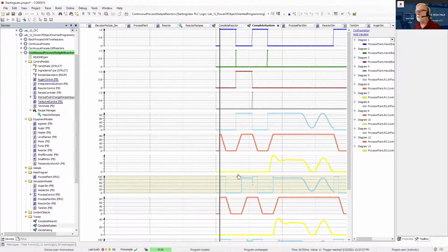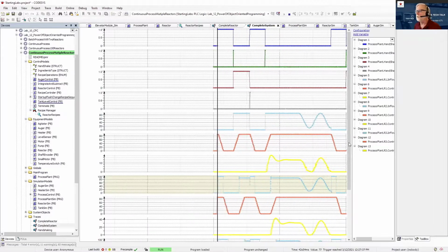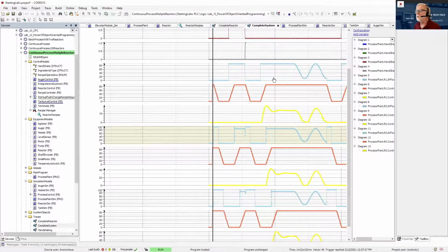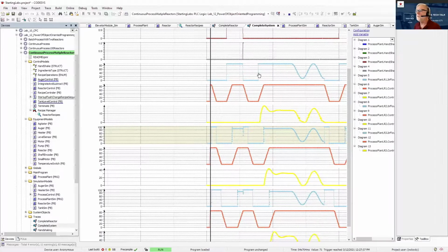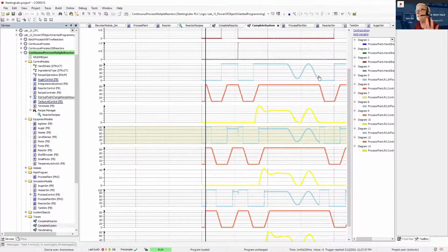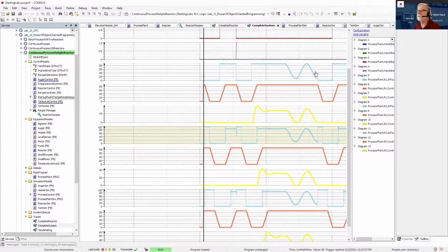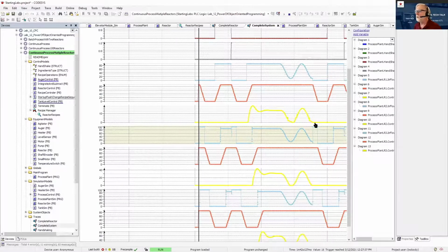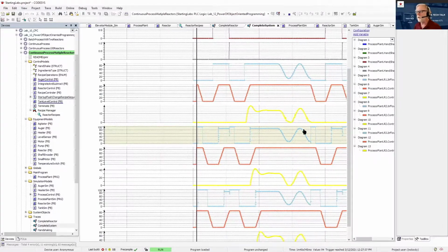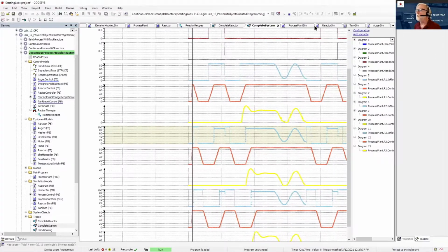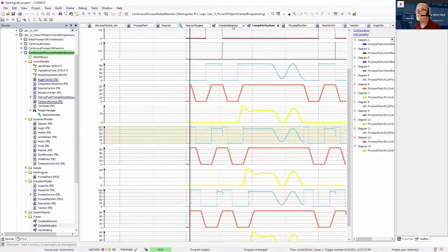Yeah, so we went through the flushing process. So this is the first tank, the second tank, and the third tank. And then this is the inlet flow rate. So it goes into a constant speed flow for a while. And then it goes into this random flow just to make sure our control loops are all working properly. And yeah, they're working properly because now the variable speed drives are all varying their speed with respect to that motor.